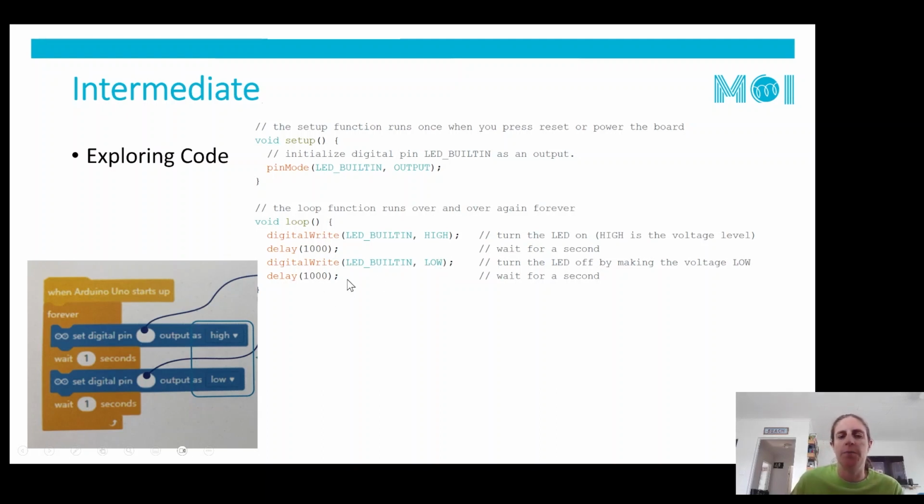So if you have multiple LEDs, you just copy that whole code, plonk it in again, and put the different pin number that's in there. So if you've got 7 for Matariki, or 9, depending on which constellation you're running off of, you could have that whole thing there 9 times, each with the different numbers, and that would all work. Then you go through and upload it, which we're not going to look at here because depending on your computer, there are a whole bunch of different ways. So just upload your code and off it will go.